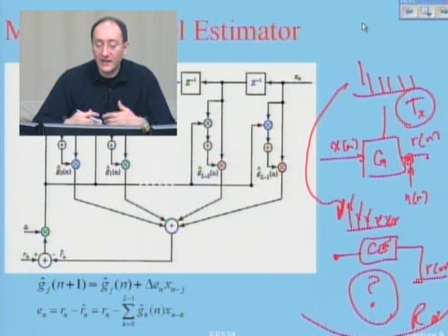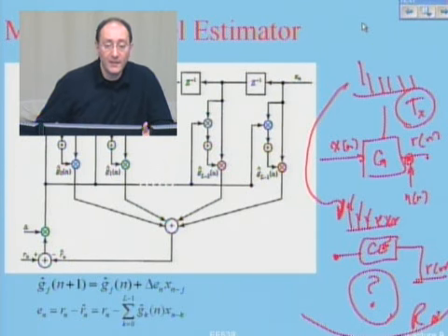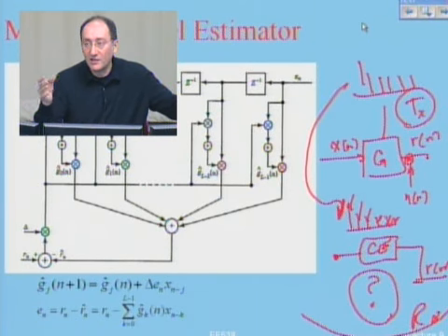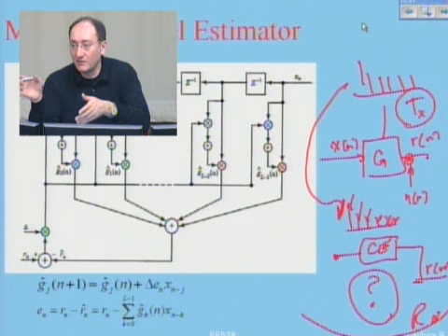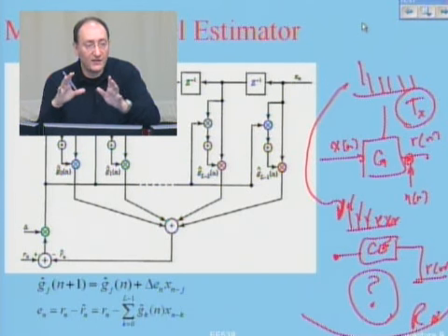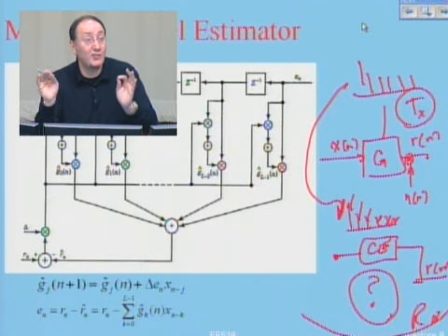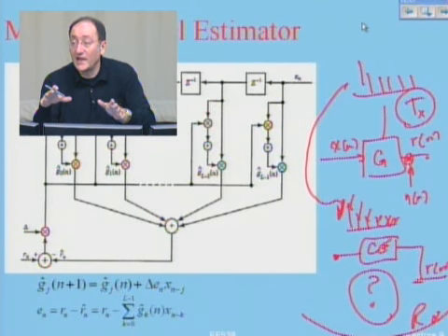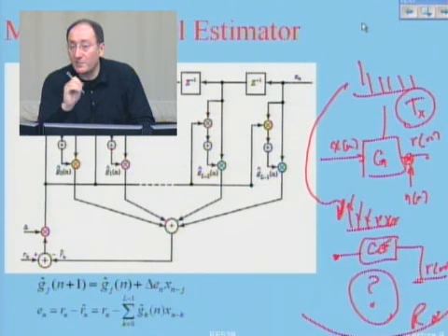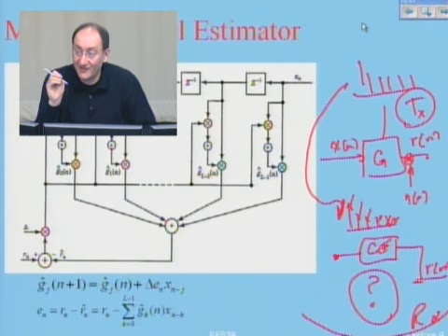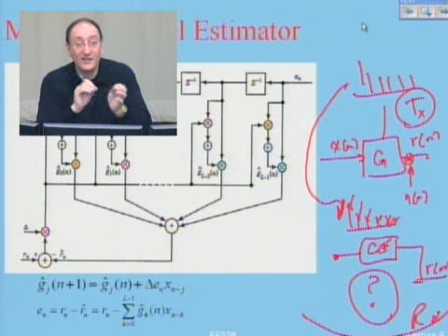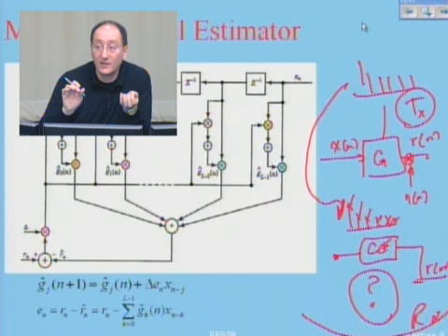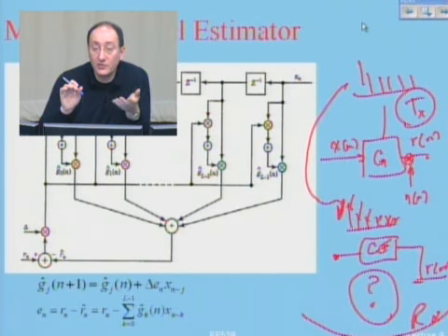Okay? So I'm looking at this system from a signal processing point of view. I'm sending a bunch of bits, and at the receiver, I'm receiving impulse responses associated with them. I have an FIR filter, I'm running that, and I can estimate that impulse response. Now, what can you do? Each tap of the impulse response is like an antenna, because they are fading differently from one another, but they are related to the same bit. So what can I do to improve this?